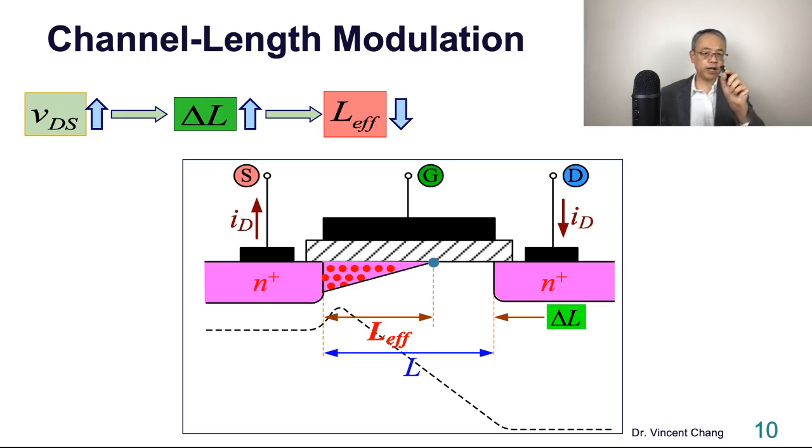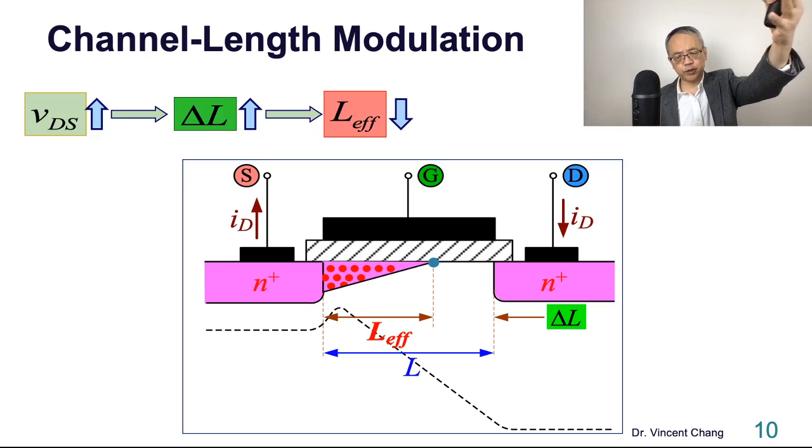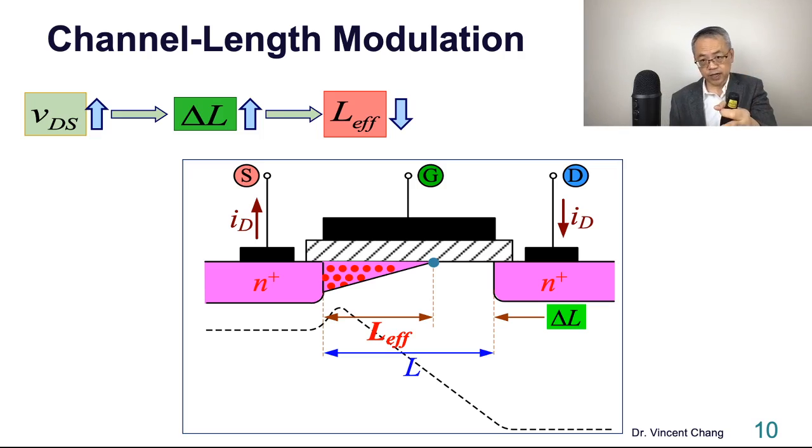But pay attention. If you go back to the previous lecture on MOSFET basics, at the pinch-off point the voltage is fixed. The voltage at the blue point, the pinch-off point, equals, you can write this down, VGS minus VT, the overdrive. So actually it's always fixed.